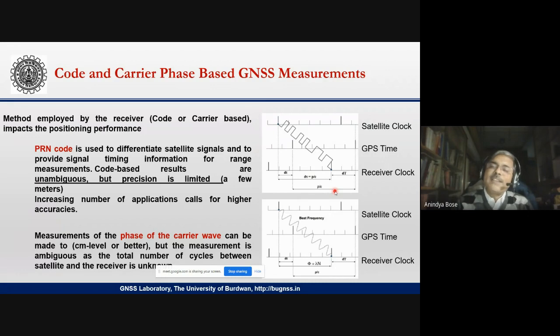In case of GPS, each satellite transmits different codes. So, for example, this is the code transmitted by satellite number 2, out of the 27 or 30 satellites. So what does our receiver do? The receiver knows all the codes: code for number 1, code for number 2, code for number 3, like that. Now the receiver tries to match the codes with the received code. One of them will match. For example, number 2 here will match.